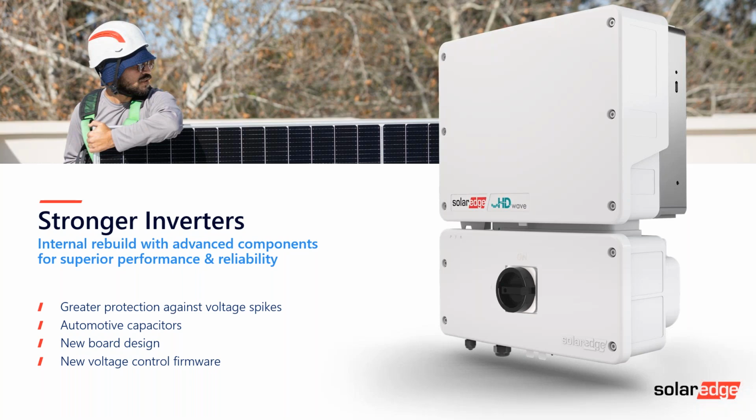So first thing we did was redesign the internals of the inverter. We moved to automotive capacitors. So these are capacitors that are produced to a far higher tolerance and have a much greater ability to handle voltage spikes that we see with the Aussie grid. We've also redesigned the way the boards are done, and also new voltage control firmware.